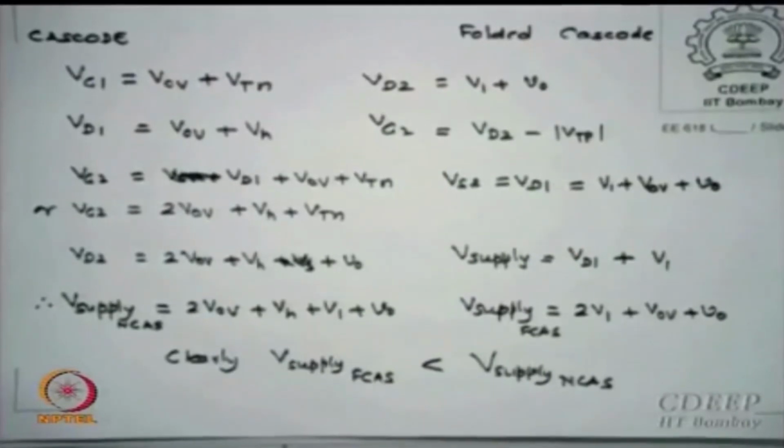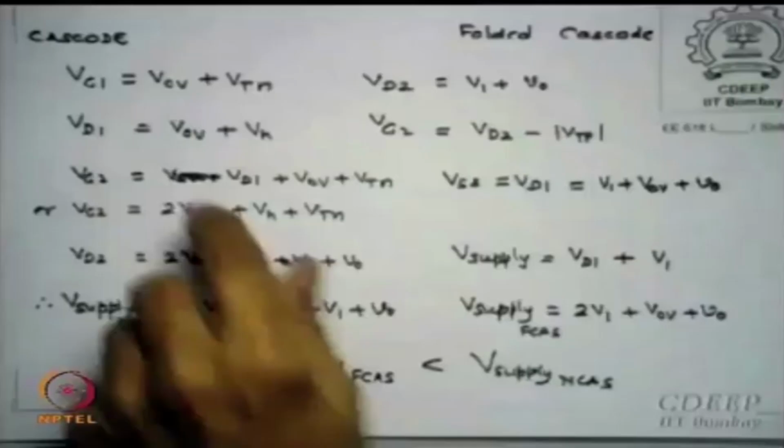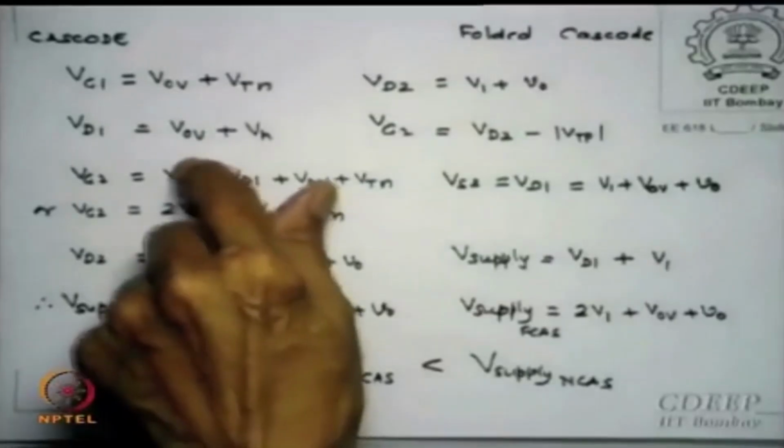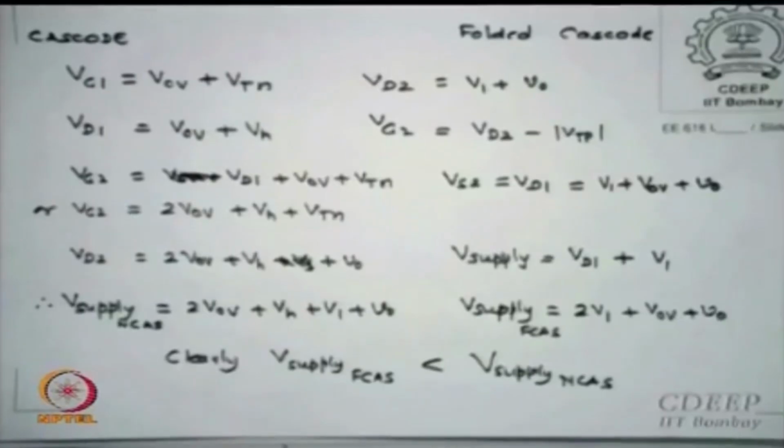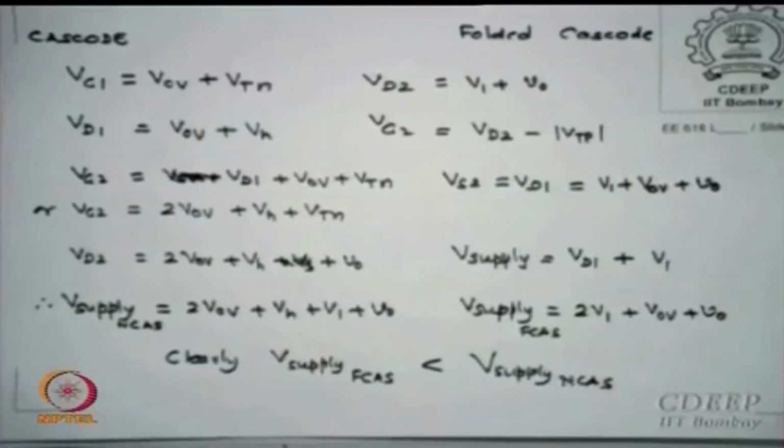It is the overvoltage, which is Vdsat, plus additional voltage which will allow the transistor to still remain in saturation. That is the limit I want to go to. So we say Vd1 is the overvoltage Vdsat plus some headroom voltage Vh. Is that clear? Why has this Vh been added? With this additional voltage, this device should also remain in saturation.